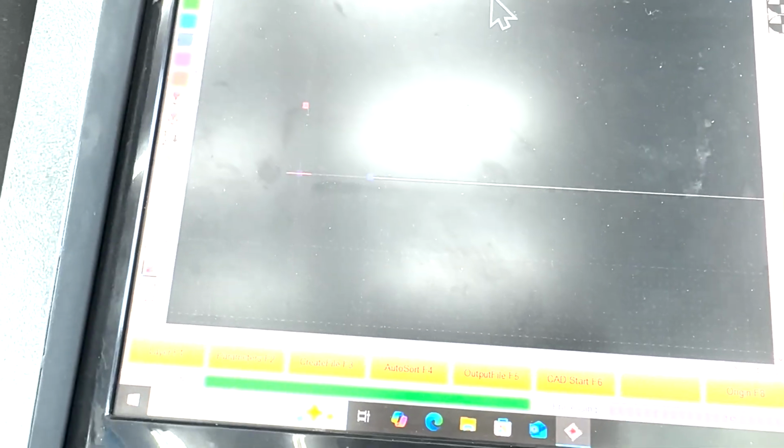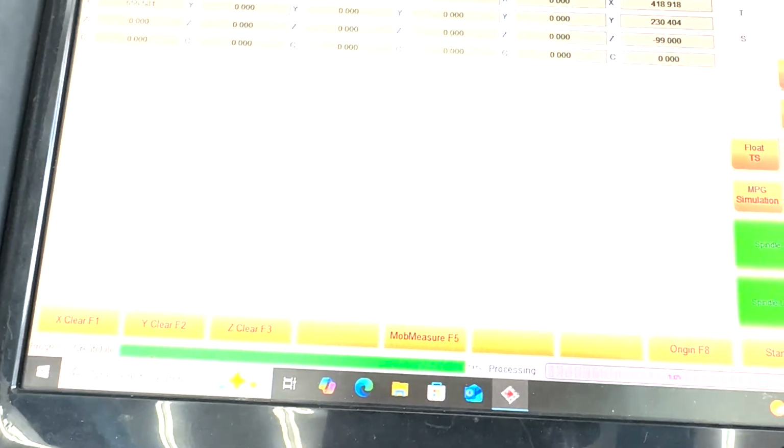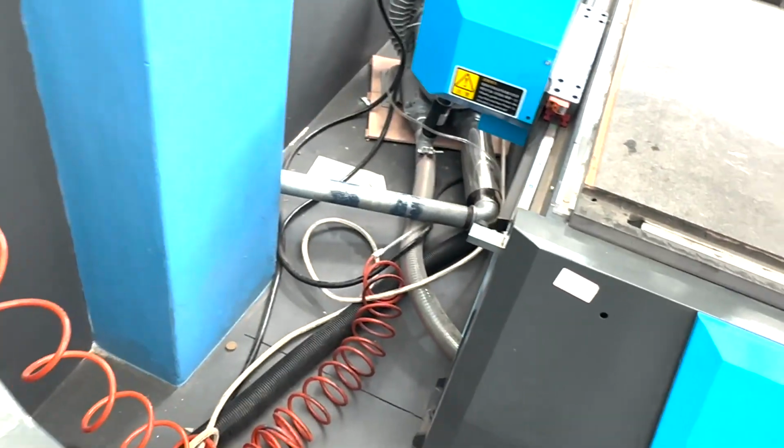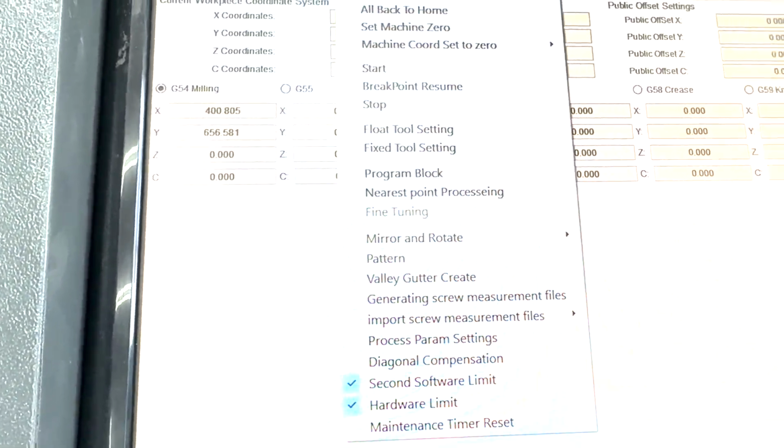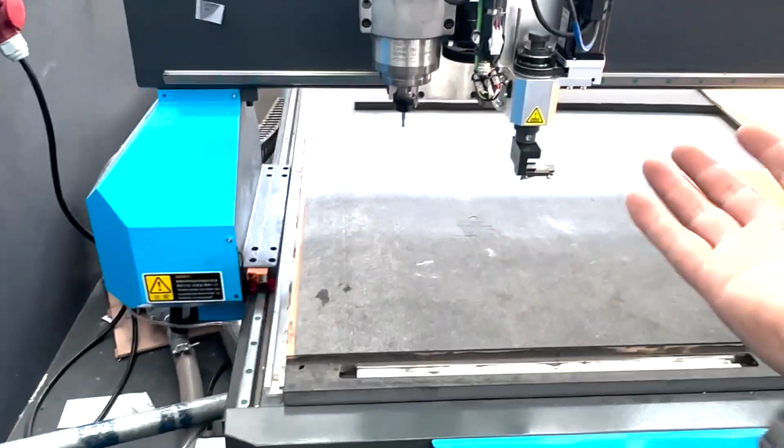First of all, we need to set the z-axis to 0, the same as touching the board, touching the mat. Don't cut so deep, otherwise you're going to damage this. Well, this is replaceable. Let's start from the beginning and reset the z-axis to its origin. Very important, when you do that, it must go down, because cutting is going down. Otherwise you're not getting the right number.